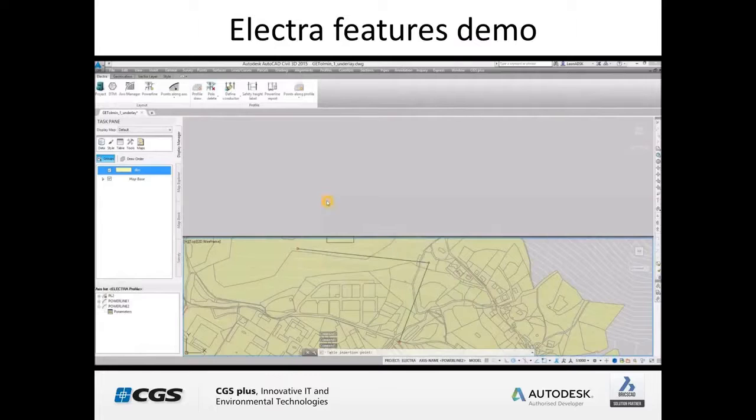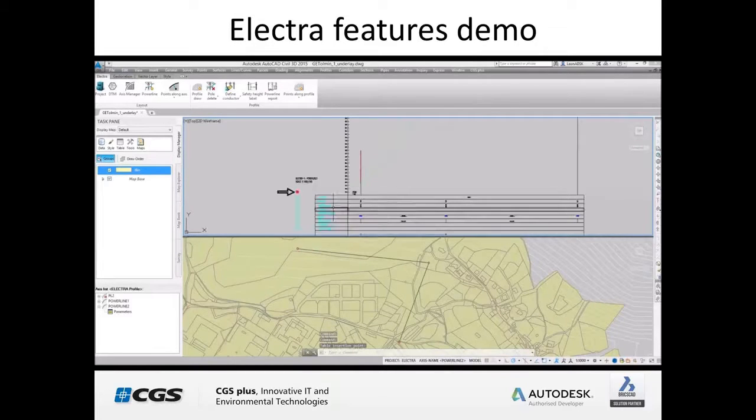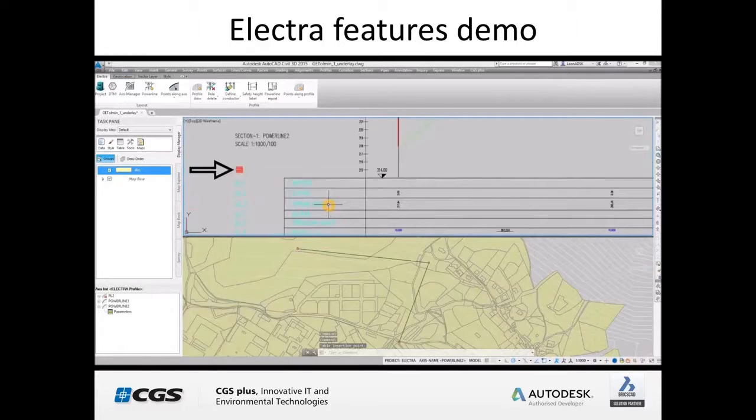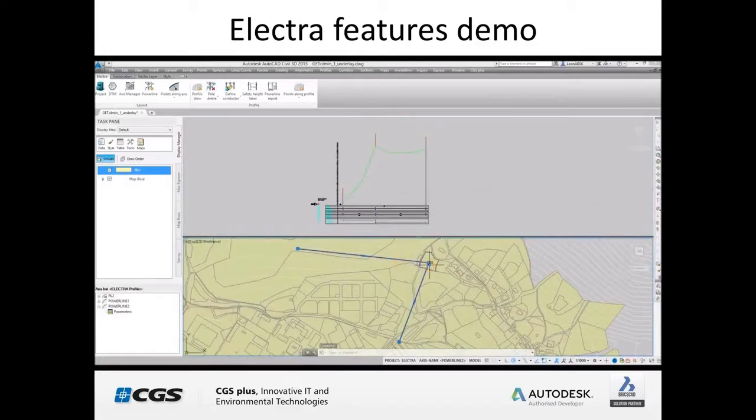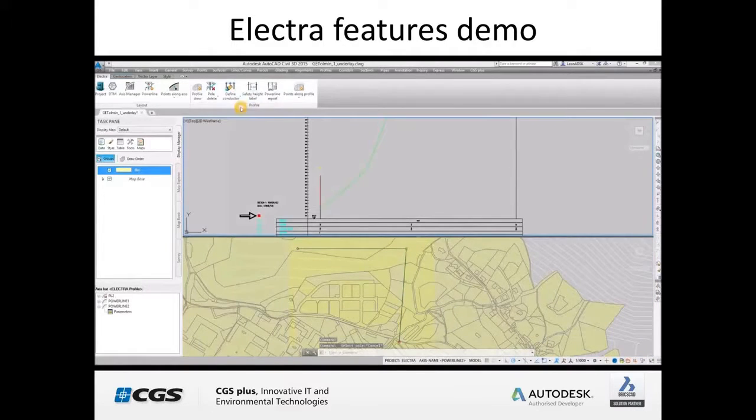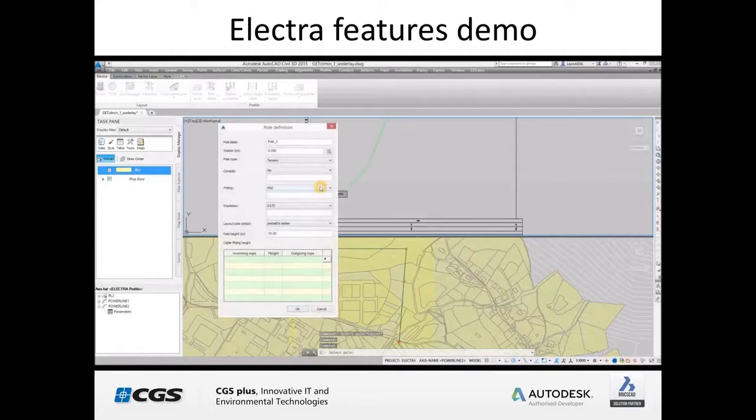We go to the profile view draw, and when we click in, like this, we get the preview of those poles already. So the beginning pole, the pole at every angle of the power line, and at the end are already predefined, but can be edited. So the user can change their height and other parameters. Also, if you can see, when we change the layout, the profile view updates automatically, and that's a significant improvement towards our software possibilities. So we will now define a conductor.